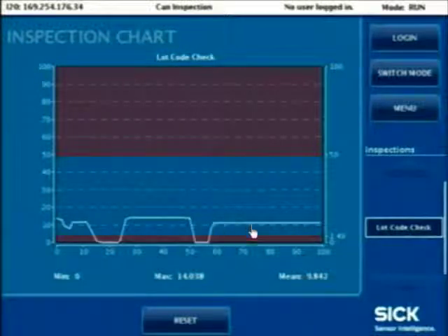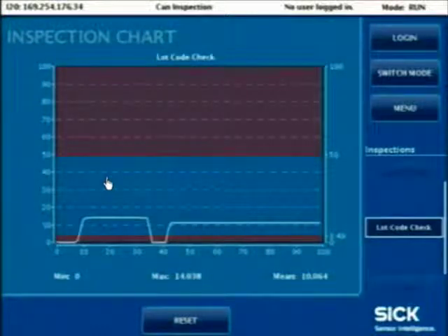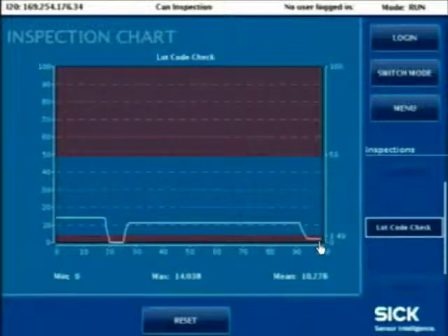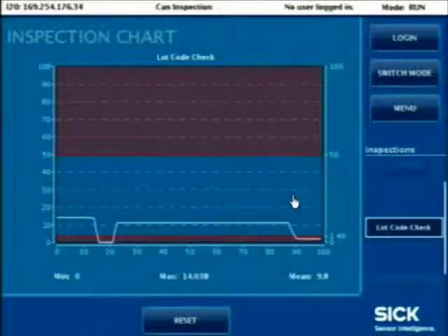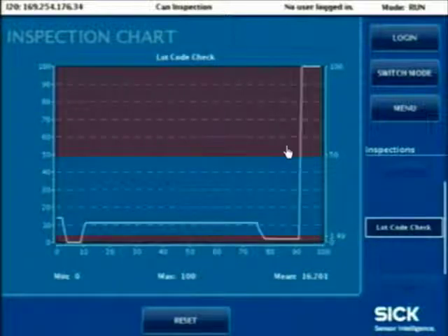And currently the inspection is passed, so you can see that my thresholds are configured between 5 and 50%, meaning that if I see anything between 5% or 50% of the darker pixels for the given region of interest that I have configured, that inspection is supposed to be a pass. And if I try to fail my part right now, my curve jumps down lower than my minimum threshold configured, or if I have too many darker pixels, then my curve jumps much higher than my maximum given thresholds.